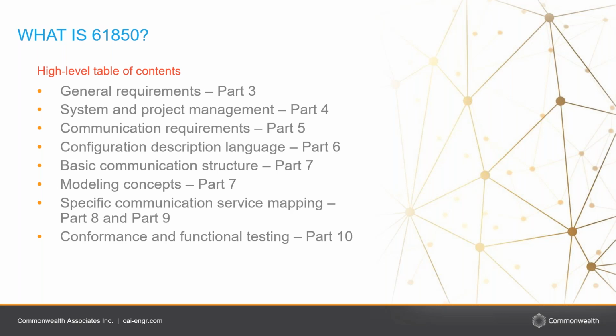Now, the standard also talks about a substation configuration language, SCL, that is based on the XML language to describe the configuration of the various 61850 enabled devices on the network. One of the major features of 61850 is abstracting the definition of the various data items and services that it can provide. This makes the data items and objects independent of any underlying protocols. I will describe more about the abstraction and data modeling on my next several slides.